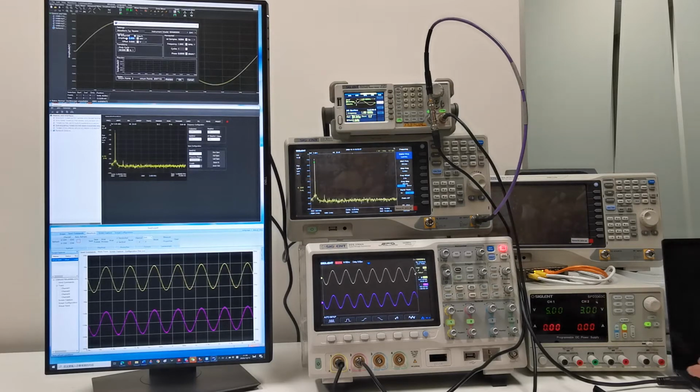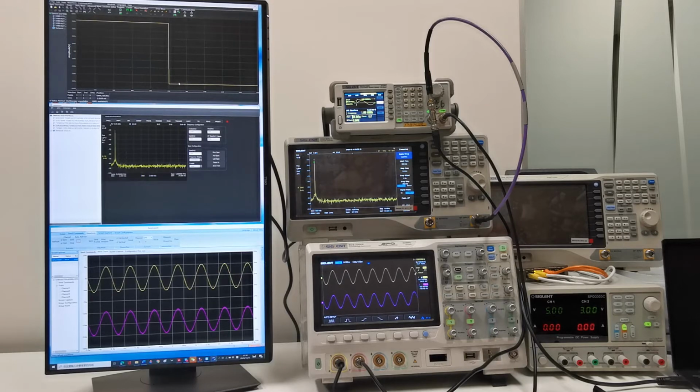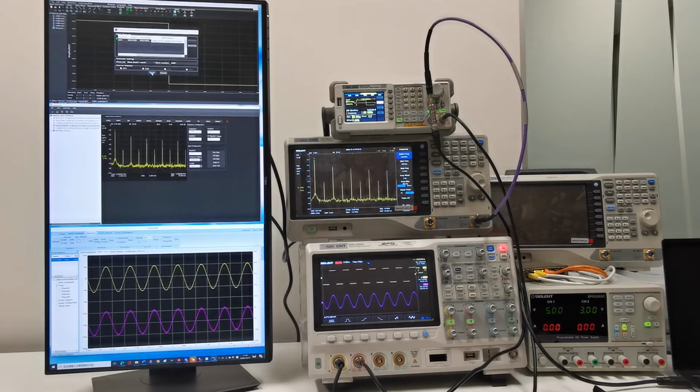But please note that the signal generator is not updated yet, because we haven't downloaded the waveform yet. So we got the waveform ready, and we have to download it to make it work. So go to download. Maybe you can't see clearly on the screen, but it doesn't matter. We will have a close look later. Okay, you can see the result updated on the spectral analyzer and the oscilloscope.